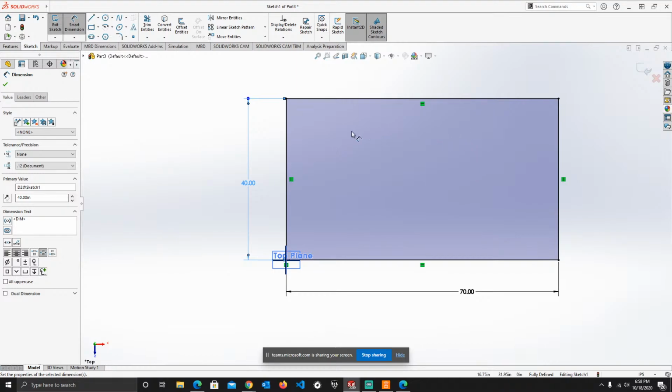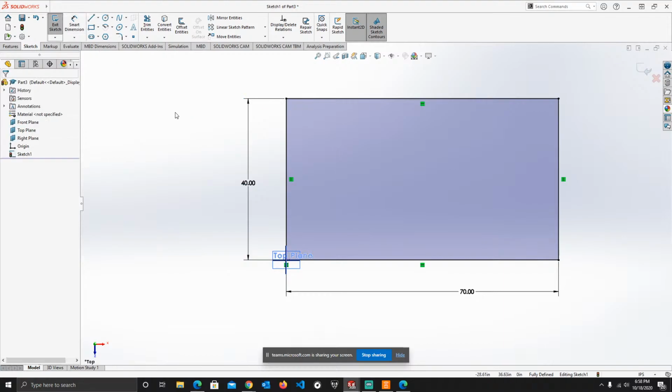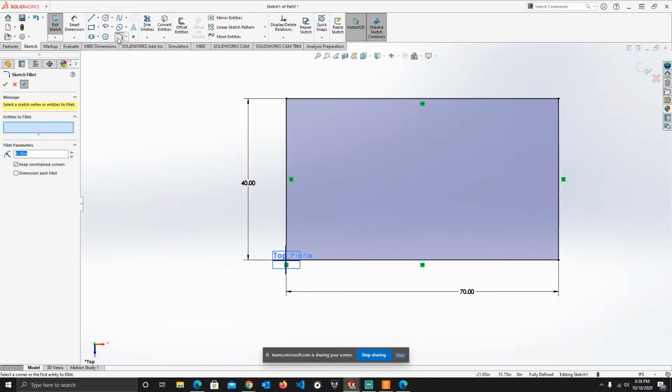Perfect. Now let's see. It's telling us that you have a fillet of 10, which in this case I'm gonna consider as a fillet of 10 inches, even though that's probably also again in millimeters. So we are not going to make our 3D piece yet. We're gonna do it here while we're on sketch. We're gonna go ahead and select this. You can also select the corner, by the way.